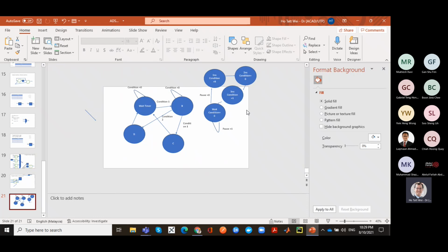Like you have a timer interrupt, or you have a countdown clock. That's nothing else than having another state machine. Okay, this is a nested state machine. The state machine is actually a counter, the simplest possible one. And when you enter the state, you enable this state machine. And once this state machine has completed, it has some condition which then allows you to jump to the next mode.